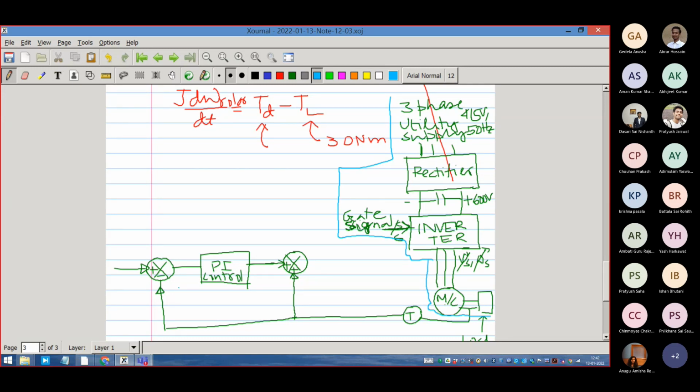Control part means it is a code, a code with instrumentation, with some instruments giving you signals. They are not power. They are all signals at millivolt level in the analog domain, and in the code domain it is just a code. After the analog to digital converter, you have taken all the analog signals. This is a measurement unit, the tacho. The tacho generator is a speed measurement unit. The tacho generator gives some voltage signal, and through some ADC you put that into your computer.